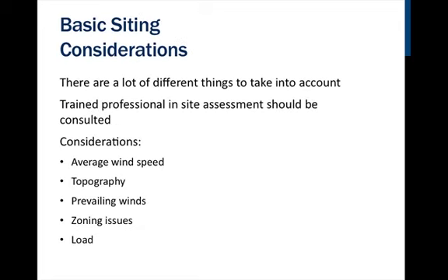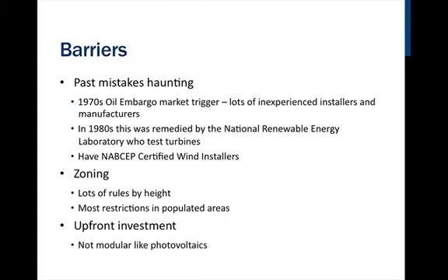Wind electric systems have even more details that need to be taken into account than PV or solar water. There are a lot of different variables that need to be quantified and assessed. It is vitally important to get a site assessment done by a professional. A site assessor, as we know, first looks at the energy efficiency measures and is trained to know all of the considerations that would affect the production of the system you want. A wind site assessor, certificate holder, is trained to understand the average wind speed of a location, topography concerns, prevailing winds, and zoning issues in your area in order to determine the right type and size of system for the site. There are more barriers to wind systems than any other renewable energy technology.